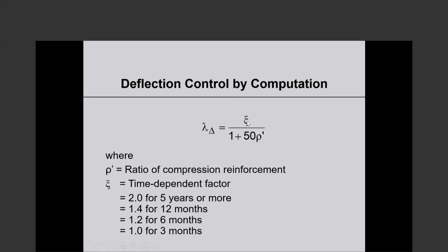If we are interested in deflections 5 years or more from the time of loading, the psi is equal to 2.